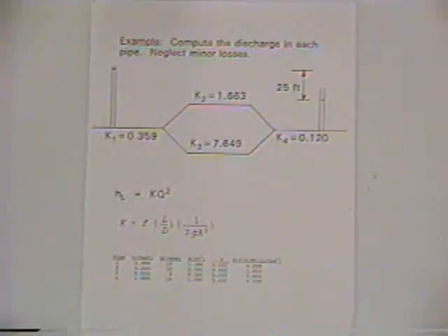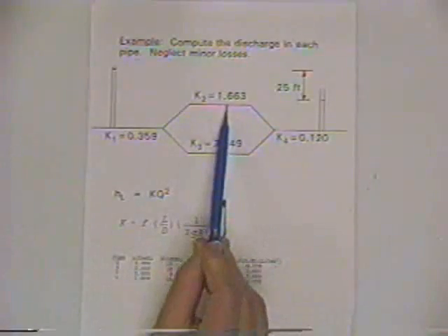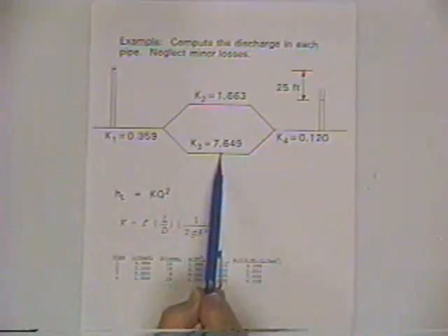Those are the concepts. And the rest of it is algebraic manipulation, which can take on a lot of different forms depending on how one wants to present the formula. So you've got to do a little bit of ingenuity to combine those basic relationships that you know to solve whatever the problem might be. And so the first thing we're going to do, we're going to say the head loss in pipe 2 is equal to head loss in pipe 3.